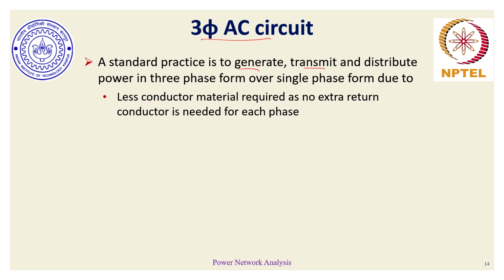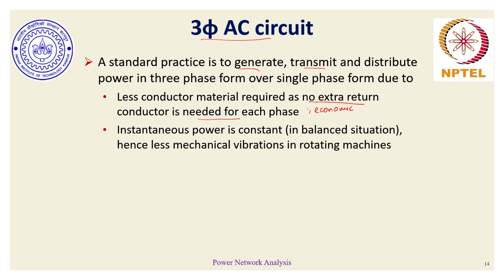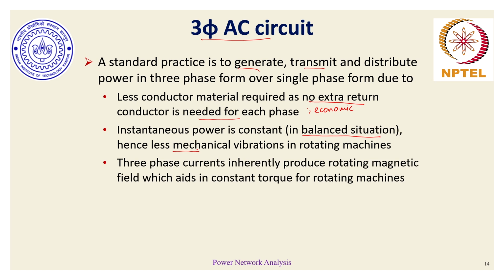Reason being, in three-phase circuits, the conductor which is required for setting up the transmission line doesn't require an explicit return conductor, and hence a lot of conductor material is saved. So, basically it is highly economic compared to single phase generation or transmission. The instantaneous power is constant under certain conditions which we call balanced situations, which we will talk about in the next lecture, and hence our rotating machines like synchronous generators and induction motors experience less mechanical vibrations.